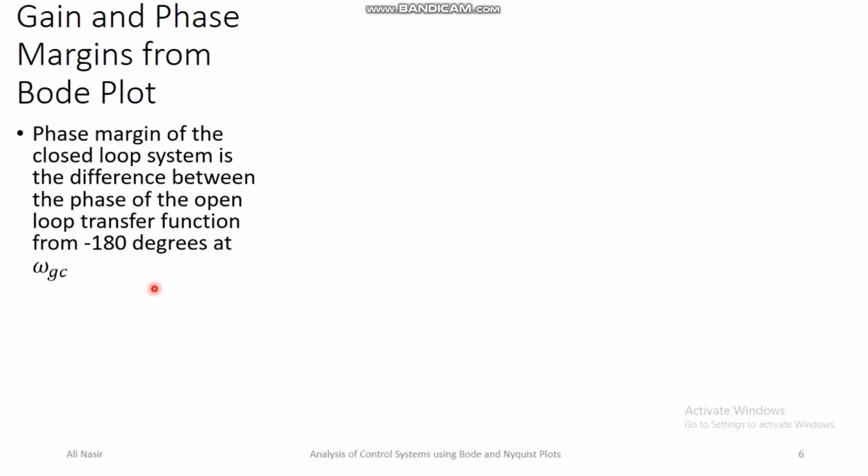On the other hand, it is quite possible that the phase of the system may be... I wouldn't rule out any possibility, because there could be many different types of systems having zeros and poles at different frequencies, and maybe there is a case where the phase is even greater than 0, but the maximum limit of phase margin is 180 degrees. So phase margin ranges between 0 and 180 degrees.